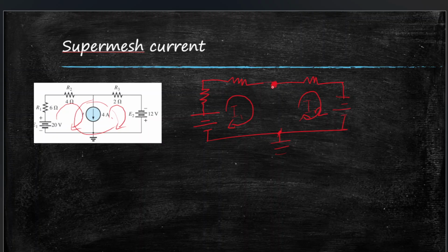Step 2, you remove the current source, and you can do it in your head with enough practice, but now, as for the first time, for easy explanation, I'm redrawing the circuit with the current source removed. So that's step 3. After polarities, step 2 was polarities, and step 3 is removing this. Now step 4 is to make a single equation using both the loop currents.